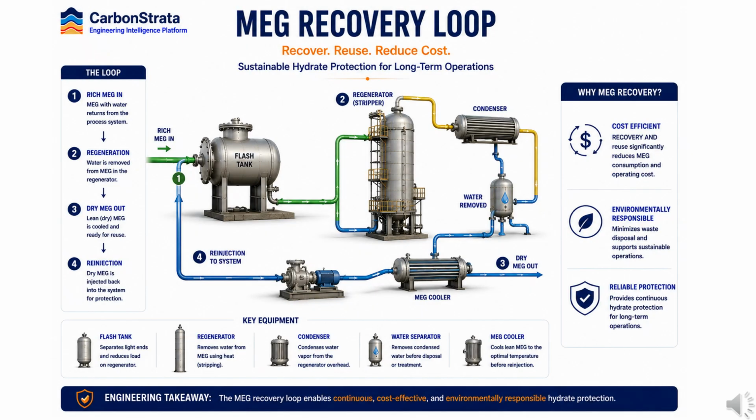MEG systems provide long-term hydrate protection in many offshore and subsea developments. Like methanol, MEG shifts hydrate formation conditions and reduces hydrate risk. However, the major advantage of MEG is that it can be recovered and regenerated. After injection, the rich glycol stream is collected, processed, and regenerated before being returned to the system. This recovery loop significantly reduces chemical consumption and operating costs.